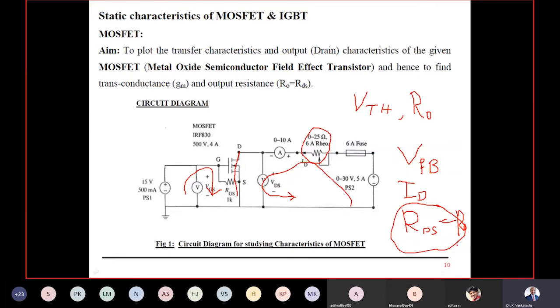So there it should be very meticulous. There will be least power, because every block of space technology may be requiring 1 watt, 2 watt systems like that. There, if the losses in the MOSFET are very high, it's a waste. I don't want to lose the power in the MOSFET. They choose RDS on to be very less. That's the importance of RDS on.